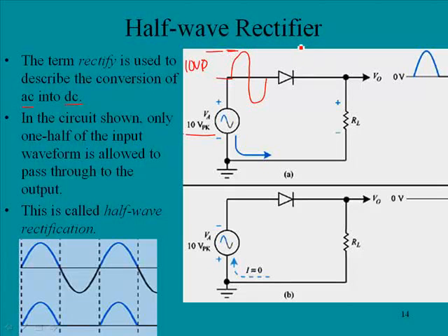And so that will forward bias our diode. Remember, our diodes, if we go from cathode to anode, the polarity needs to be a negative to a more positive, at least 0.7 volts worth, and that will cause this diode to conduct, and it will pass this signal. And so we will have this AC signal passed over. All of it except for the 0.7 volts will be passed to the output.